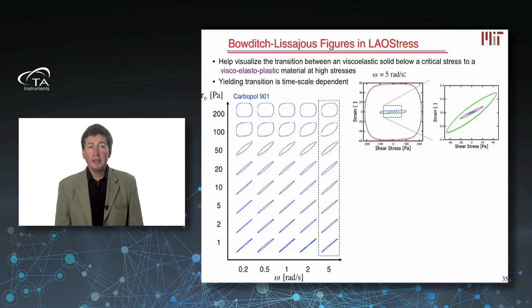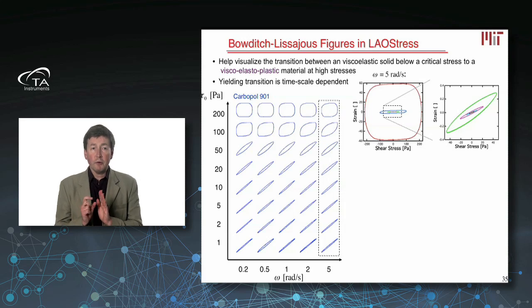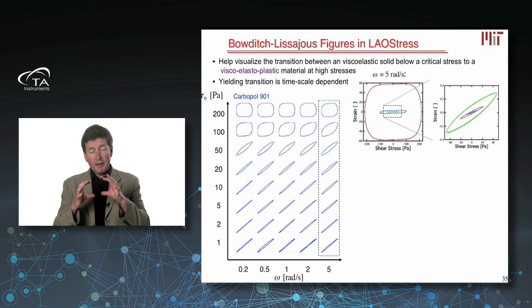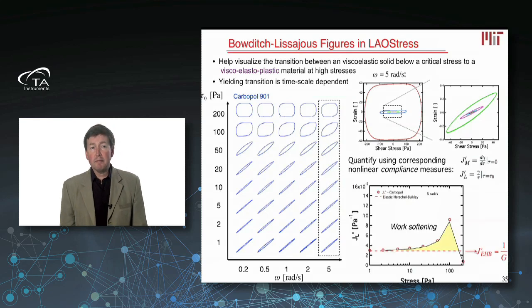And so I've shown here the strain on the vertical axis, the stress on the horizontal axis, and you see that the linear range in these materials is very small. Okay, so at small stresses, the material is linear, but then as you go to larger stresses, suddenly the strain increases a lot. And the way that's captured is by thinking about the area of this curve, so the area captured by this curve. I can plot any measure of this curve.